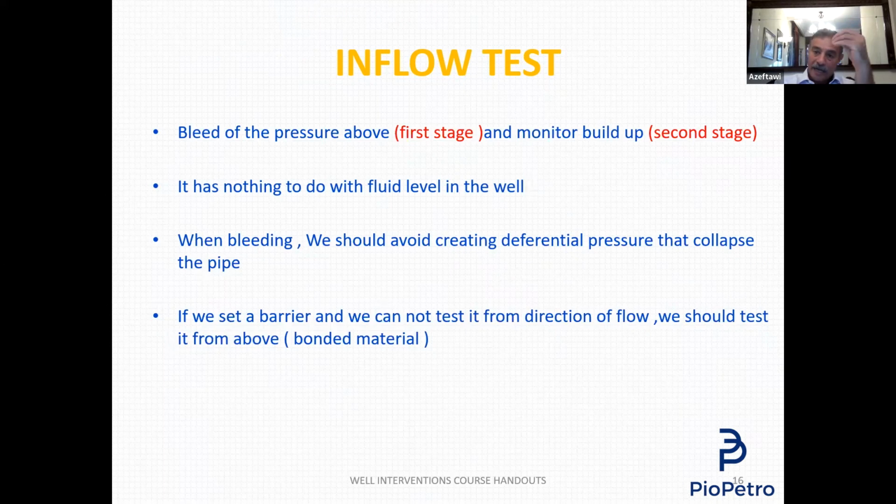Let us have a plug now, a wireline plug, that we set deep in the well in the tailpipe. What is the tailpipe? The tailpipe is a part in the completion. The completion is a series of pipes connected together with a lot of accessories. And they have what we call a packer.